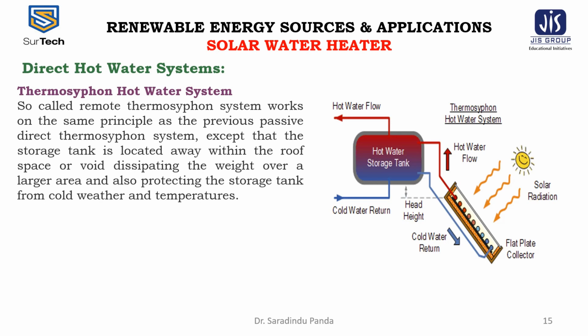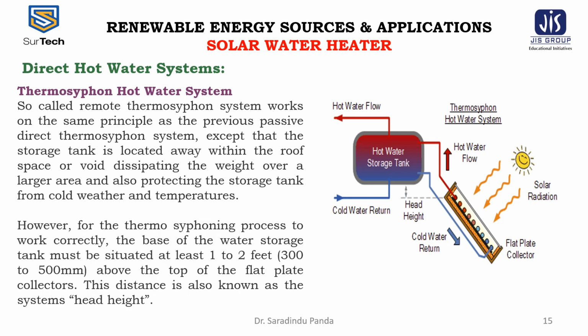The so-called remote thermosiphon system works on the same principle as the previous passive direct thermosiphon system, except that the storage tank is located away within the roof space or the void, dissipating the weight over a larger area and also protecting the storage tank from the cold weather and temperatures.